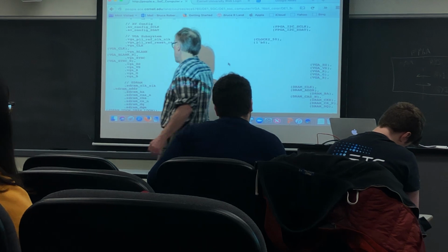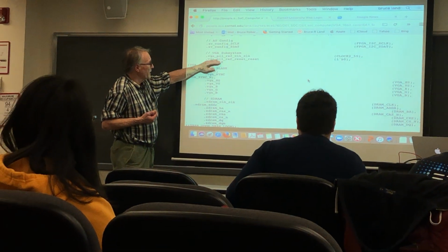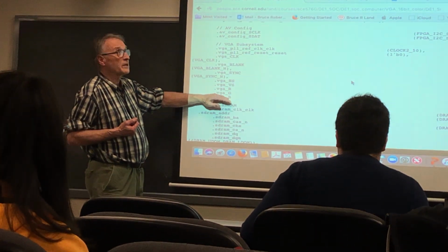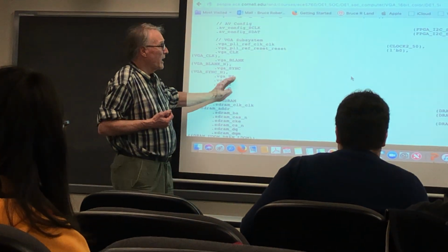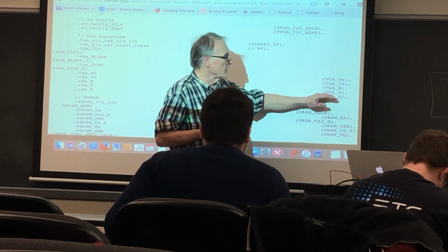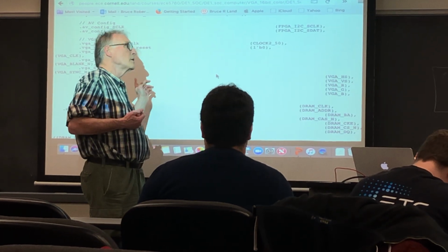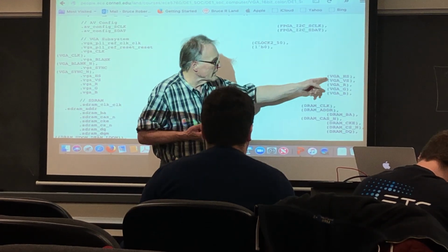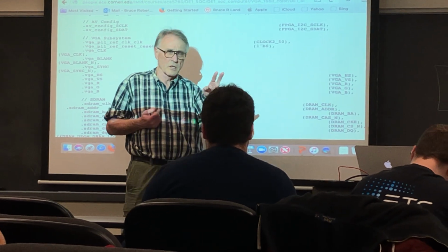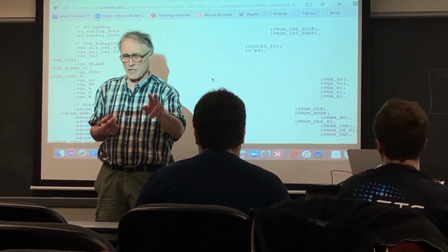The exported signals, for instance, for the VGA subsystem are here. These are the names that you associated with the signals in Qsys, and these are the connections to the outside world. In this case, we're merely taking the output from the VGA control system and hooking it directly to the H-sync, V-sync, and RGB controls of the monitor that you're going to attach to the FPGA.